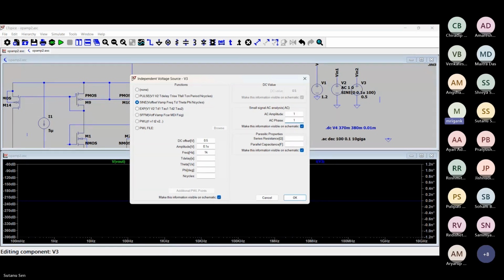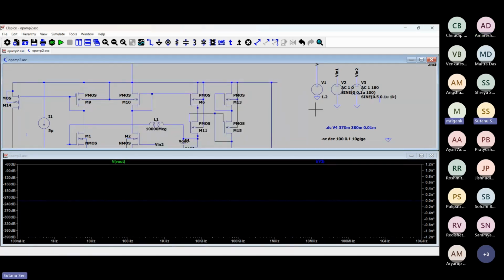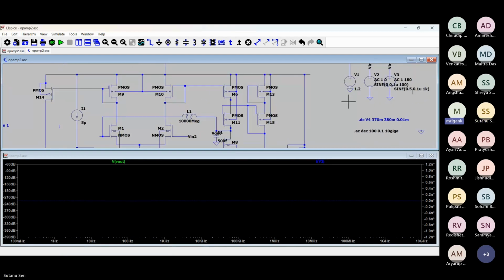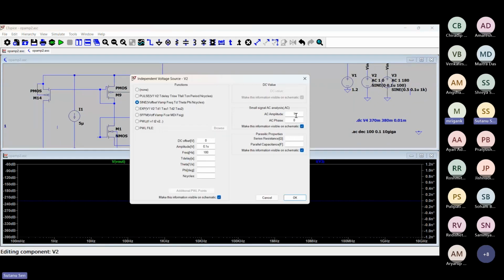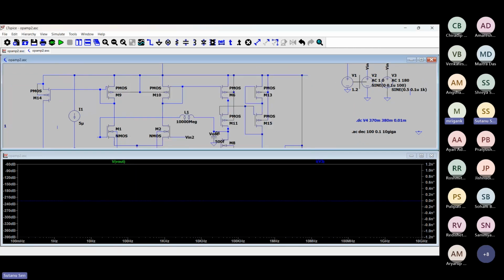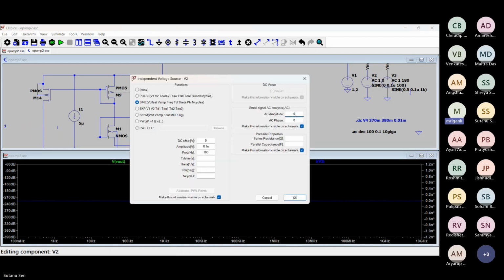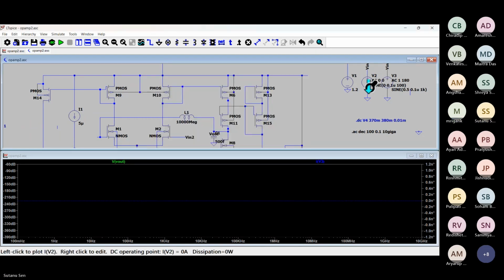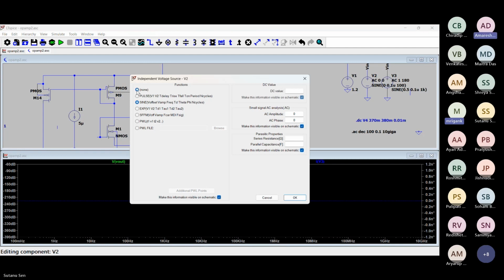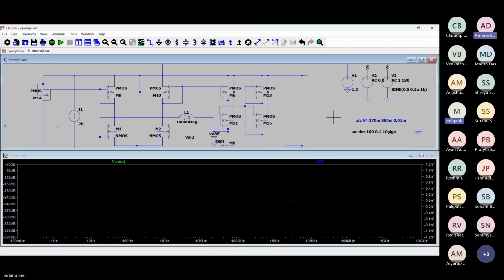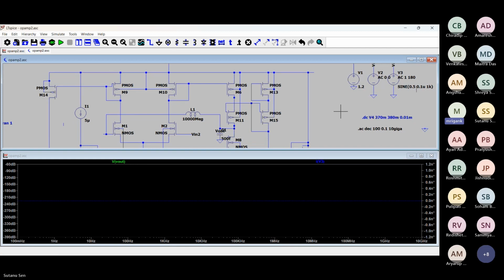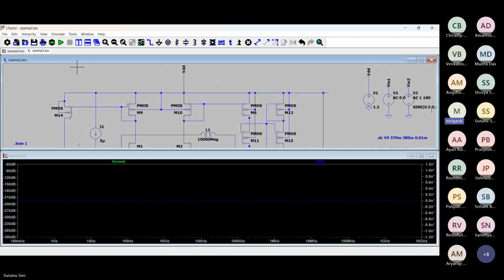So open loop analysis, the way you are doing right now, requires an STB and a DC point calculation. First, you try to find out the appropriate input DC level so that the output is at the midpoint, and then do the AC analysis. But using this approach, you're not getting that. From the DC point of view, just look at the DC voltages at different points.